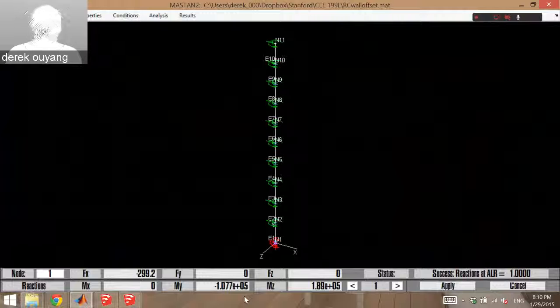Probably not going to have to worry about that in 183, but that's just something to keep in mind, that if torsion ever comes up as a topic, of which it might, these are the sort of dangerous things we're talking about, where you're getting a double effect from the basic bending moment you've already calculated, and then the effect of torsion on one specific part of that piece.